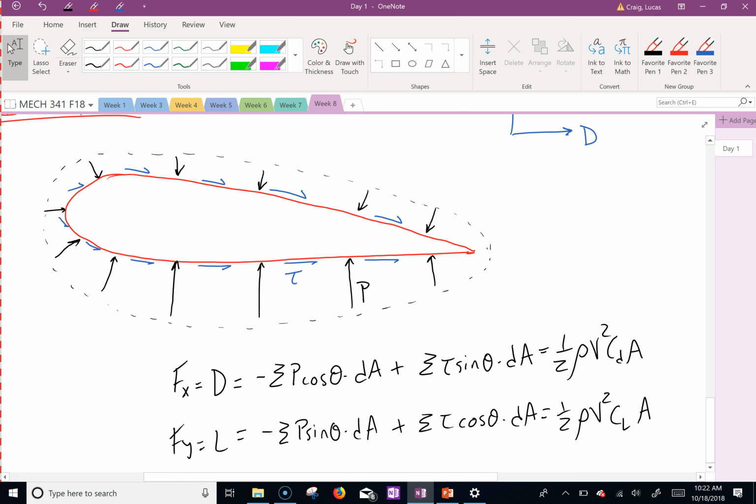Do we want control from the top and the bottom? It doesn't matter, because as long as you know if it goes up or down, you could figure out that lift. For example, I have a regular scale. If you build a wing and you mount it and you put it on the scale and you turn a fan on and you blow it, if the scale gets negative values, you get lift, right? Because it's lighter. Or if it goes positive, it pushes down.